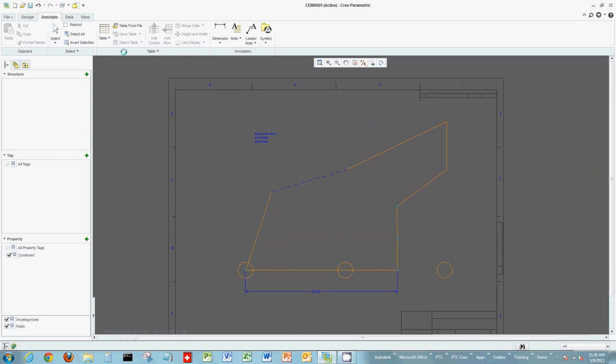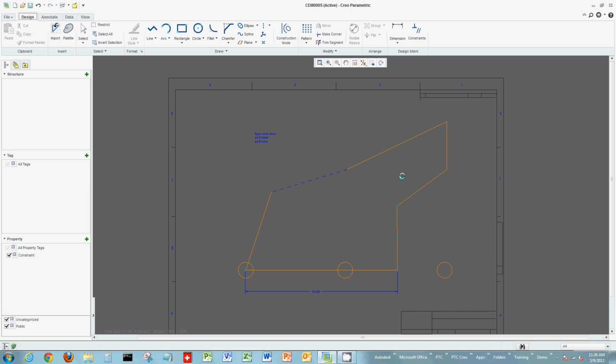Now back to some of the other sketching tools. You can copy and paste. So I can simply just Control C and then Control V, and I copy and paste an element, and I can move it where I want to, reorienting it, in this case realigning it to different elements throughout the actual tool. You can also mirror elements. So if I have a mirror centerline, I'm just creating a geometry or a construction centerline here within the shape, and if I want to mirror an element about it, let's say I want to mirror this line on the left. Well, I can select the line, choose my mirror tool, choose the centerline, and I can mirror that element about the centerline. So I have the full capability to change those elements.